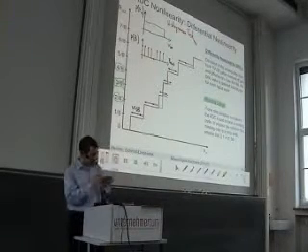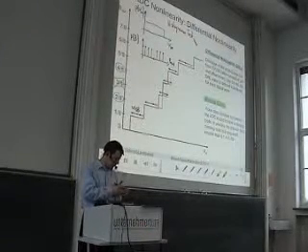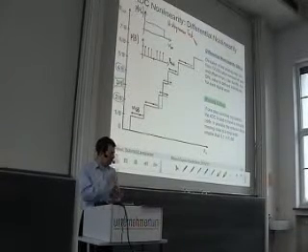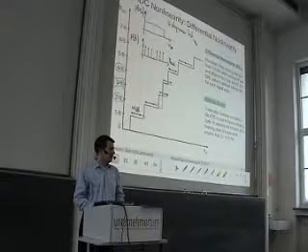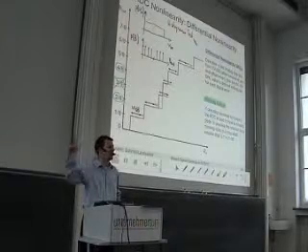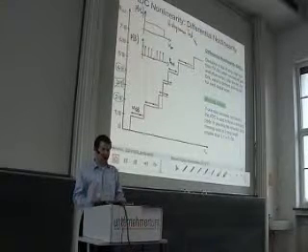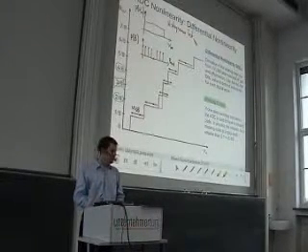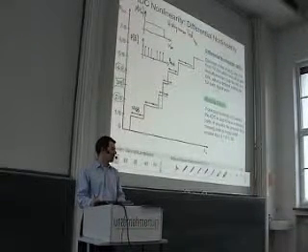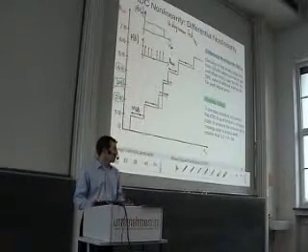So if you are in the lab and measure the characteristics of an ADC, for instance, then you apply a certain voltage, measure the value, increase the voltage a little bit, measure the value again, and increase the voltage, measure the value, and so on and so on. And then you plot all these values. And unfortunately, you never get such a step characteristics because all measurements are a little bit disturbed by noise. So sometimes you get a value that is one too large, one too small, but you get an awful characteristics that does not look like steps, but has several intermediate steps.